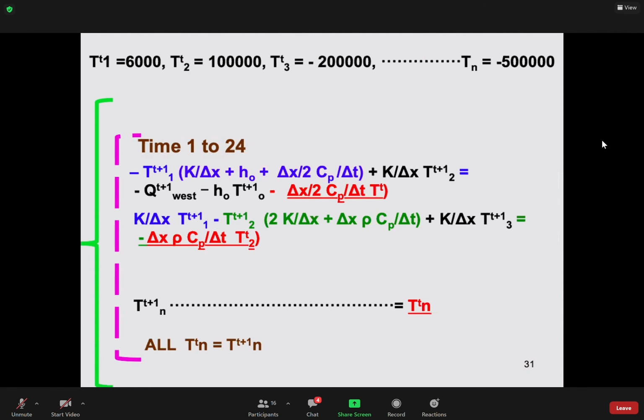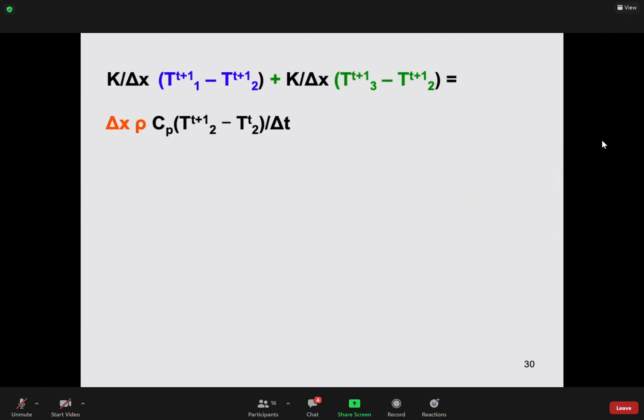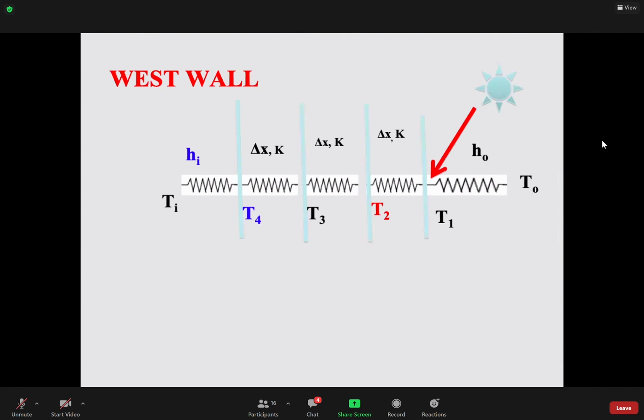No, it doesn't work because whatever number you start with, you can guess. I mean, you can because it's transient, and transient means the temperature changes as a function of time. You will see it in your result. Therefore the temperature at node 1, node 2, node 3, all of them will not reach the max at the same time. In a steady state, when you did it, all the temperature maximums were almost at the same time, because we assume whatever is received here is immediately passed. But here, some of the energy we store here, and the problem moves to the next hours, and part of the next.